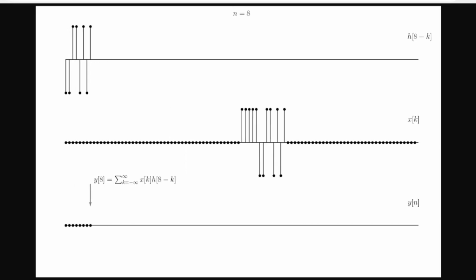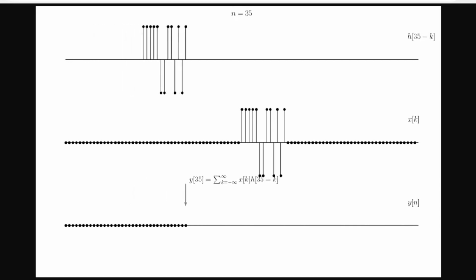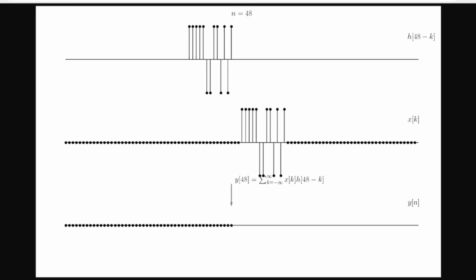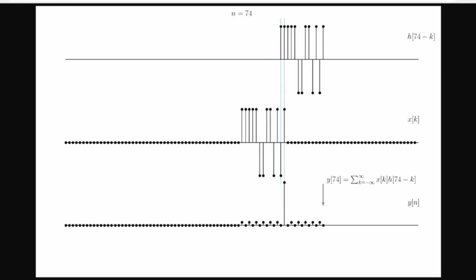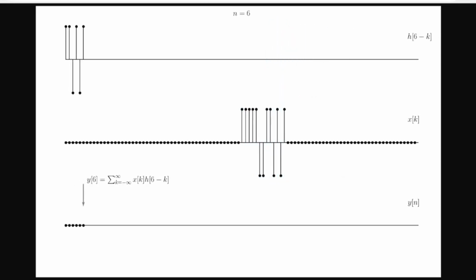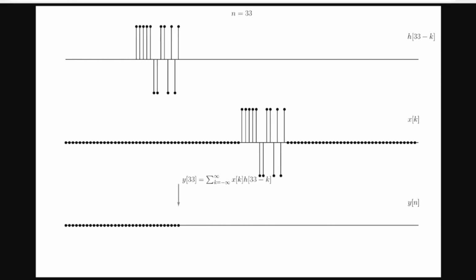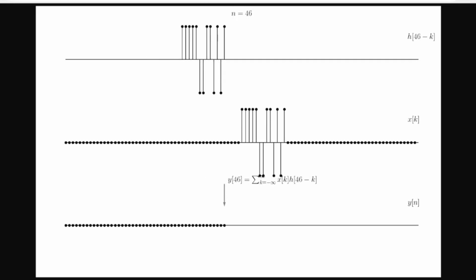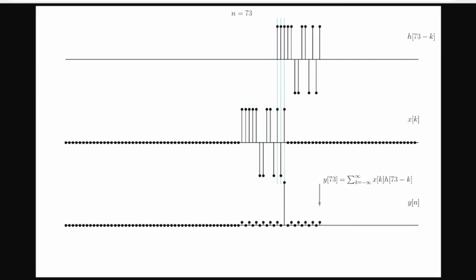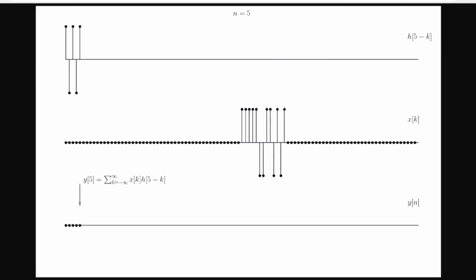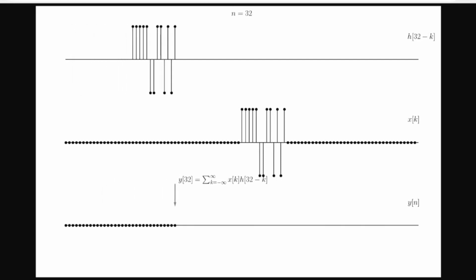This animation demonstrates the use of a match filter. In this case, the match filter is a conjugated version of the transmit signal itself. The match filter is shown above. The 13-bit Barker code is a fairly good transmit code. However, our estimate of scattered voltage as a function of range has bias, as you can see below. This bias is due to the autocorrelation function of the transmit code having non-zero values at non-zero lags of the autocorrelation function. These estimation artifacts are called range side lobes. They can typically appear around a strong point-like radar target when using a match filter.